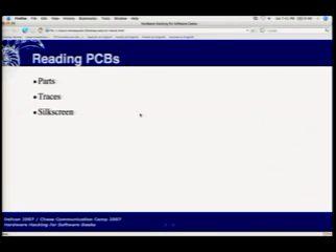I have a monocle sort of display that was set up for PAL, but I opened it up and looked at the circuit board, and I noticed that right next to the resistor that sets "this is a PAL video input" were a pair of empty pads. Looking at the data sheet, I found out that sets NTSC, and I got it to work better with US equipment as opposed to the rest of the world where they use PAL.